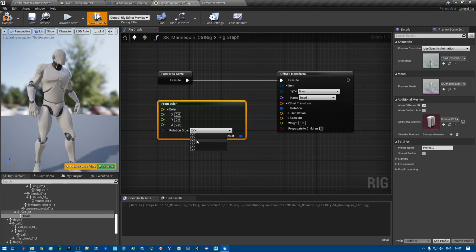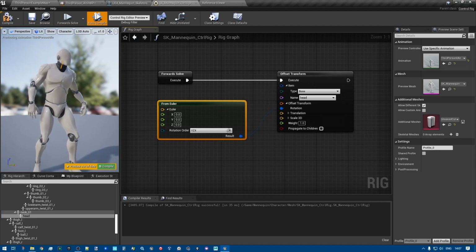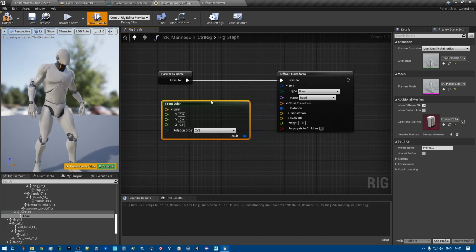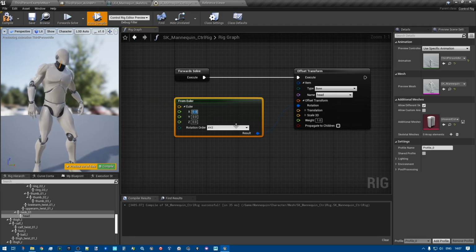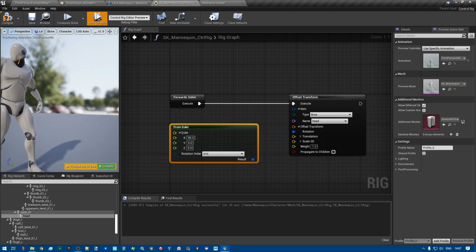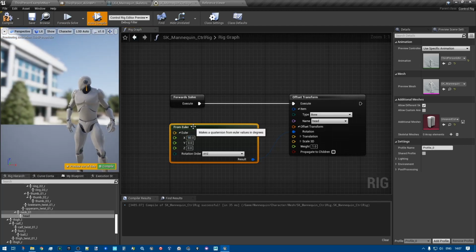If you want to rotate all the way from minus 180 to 180 around the y-axis, you can choose this rotation order, and you will not have the gimbal lock problem on the y. You will have it on the z. That is just a side note. So let's rotate this head like so, or like so. Now it works.